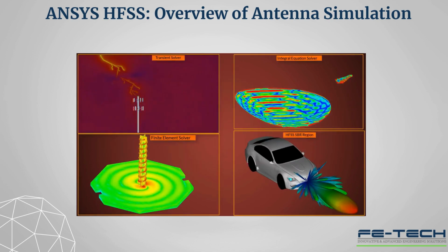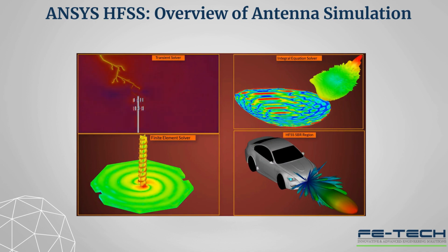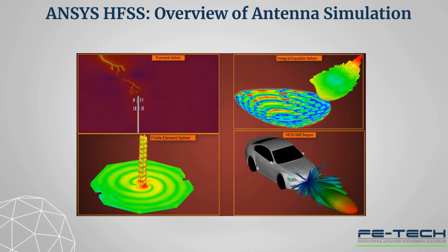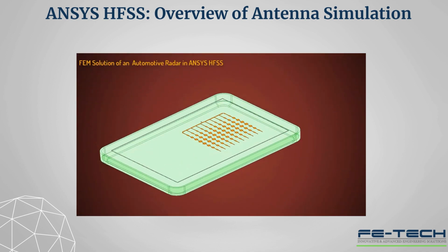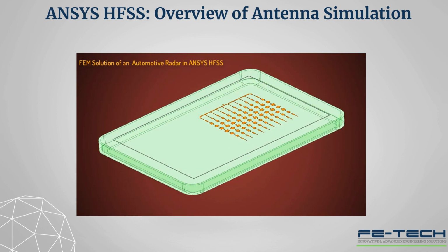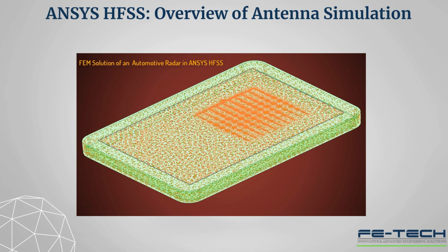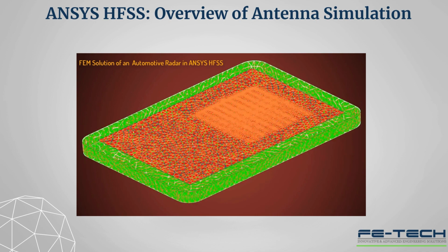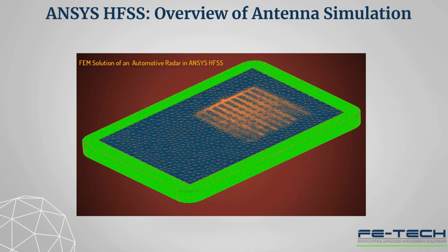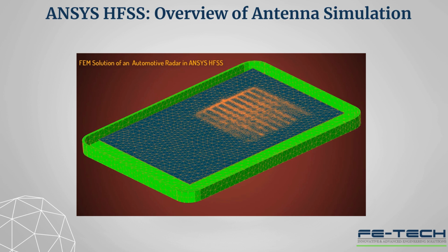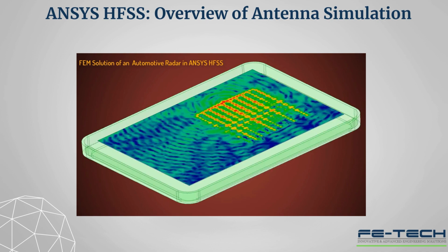Depending upon the geometry, material complexity, and the electrical size of the problem, you can accordingly leverage the strength of multiple solvers in ANSYS Electronics Desktop. For instance, finite element methods, or FEM, can handle geometries of arbitrary shape and high degree of material complexities efficiently. In this method, the model is divided into tetrahedral elements conformal to all surfaces of the geometry. The model is represented with a volumetric mesh and solved to produce field solutions.